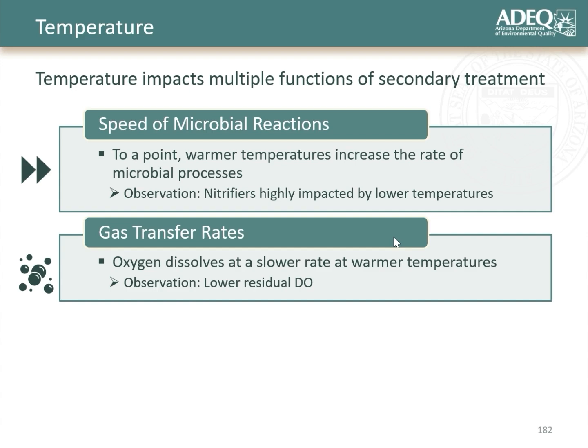Temperature also changes your gas transfer rate, because as the temperature warms up, the maximum amount of dissolved oxygen that the water can hold drops. So as it warms up, your residual DO in your system could lower as well. So that's another thing to think about in terms of how temperature can impact your performance.